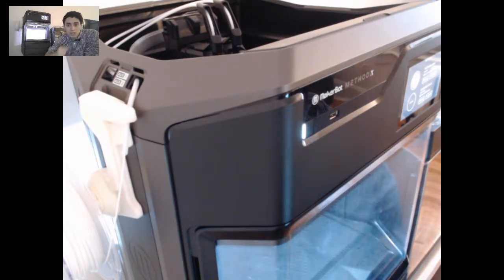If I leave my filament loaded inside of the printer for an extended period of time, will my prints or extruder get compromised? No, but I would say if you're leaving your printer idle for more than a week, do consider putting your filament in a Mylar bag instead, just because that will keep your material much drier and in a better state for you to use. The extruder will not have any issues, but the material, depending on the material, can soak up some moisture and then degrade over time.